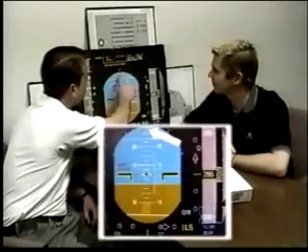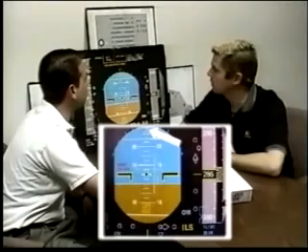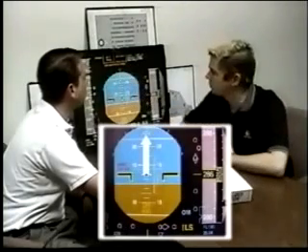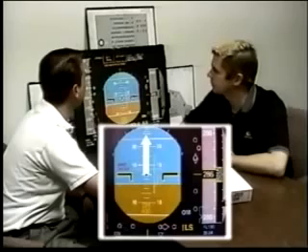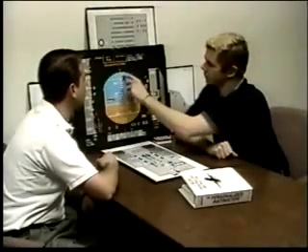What's your yellow triangle up here? The top part is the sky pointer or roll index, and the bottom part, the bottom trapezoid, is called the side slip indicator. Okay, it's yellow, so it's a side slip indicator. Will that ever change colors? Yeah, it could be blue when it's the beta target. Okay. Now, would you still center the beta target up? Well, if you center up the side slip indicator, you're asking for zero side slip. And if you have the beta target centered up, you're asking for the optimum side slip for the asymmetric thrust that's going on. Beta target's only available, we have a gauge called 1, 2, 3.